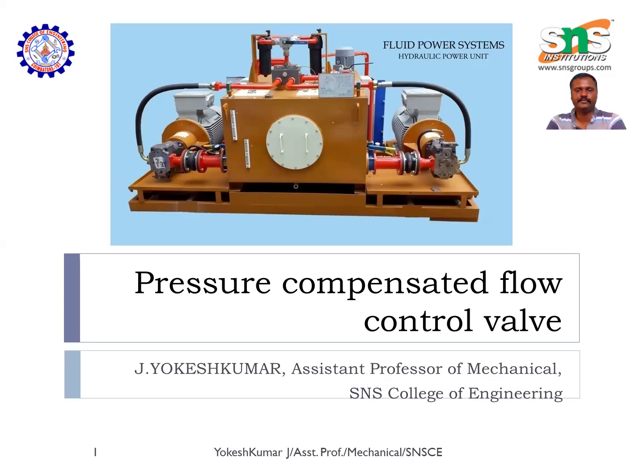In the previous video, we discussed the non-pressure compensated restricted type of flow control valve, that is the needle valve, which is used to control the flow rate, where pressure compensation is absent. Because of that, whenever the load changes, the flow rate can vary. So we do not have control over the flow rate in the needle type of valve.